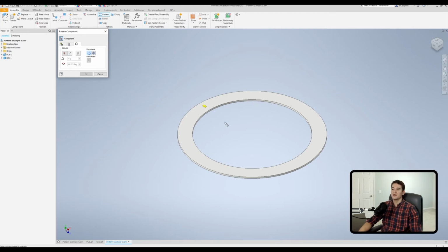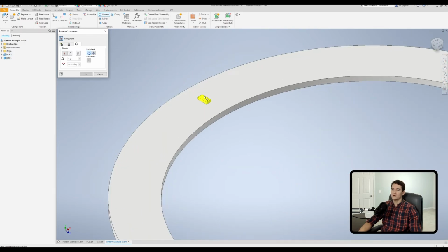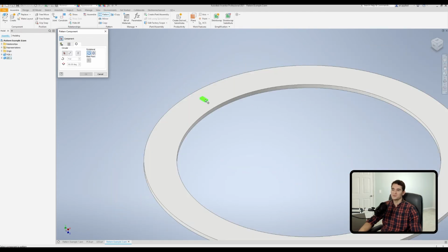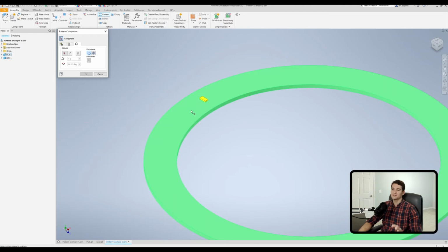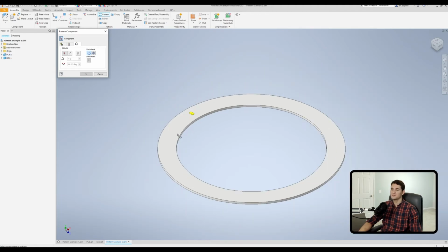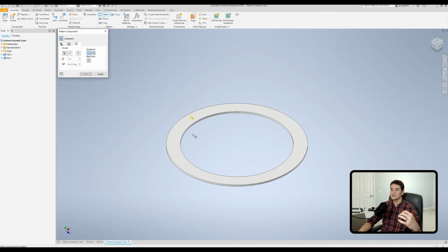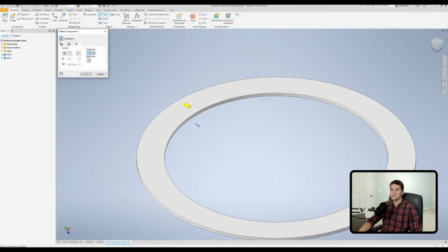Okay, so this consists of our printed circuit board profile and our LED. This is a surface mount LED that's soldered on to the surface of this particular PCB. And this can be done either via pick and place, or it can be done with a solder stencil. So anyhow, what we want to do first is select our components of interest that we want to pattern. In this case, it's just the LED. So we'll select that.